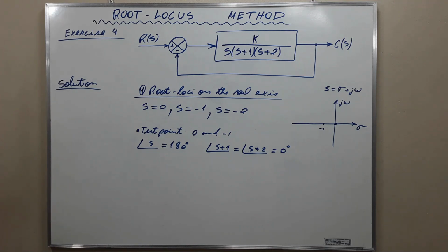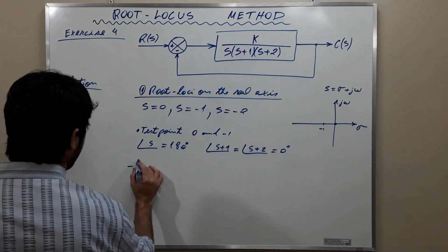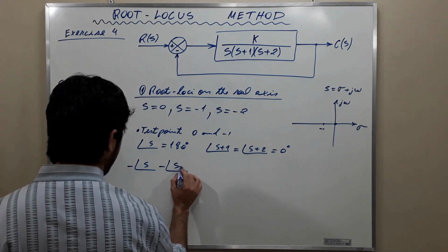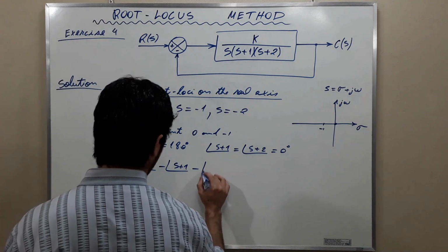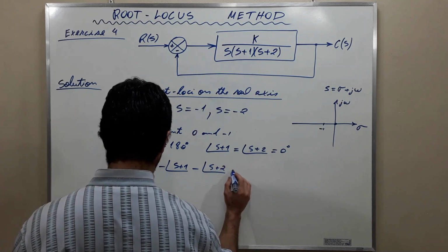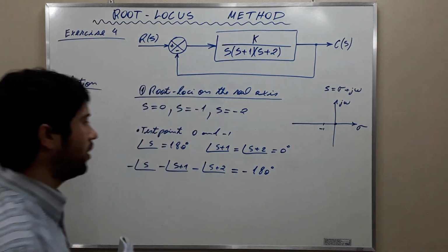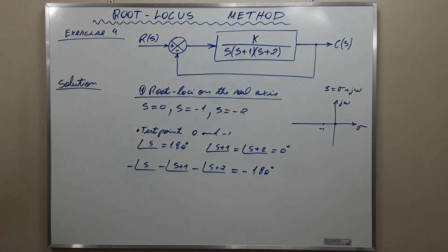In accordance with the angle condition, we verify that it is satisfied, because minus the angle of s minus the angle of s plus 1 minus the angle of s plus 2 is equal to minus 180 degrees. And thus, we conclude that the angle condition is indeed satisfied.